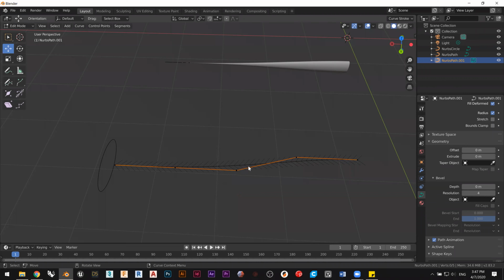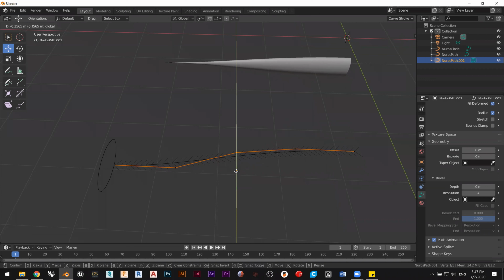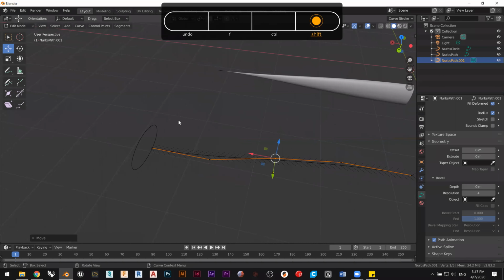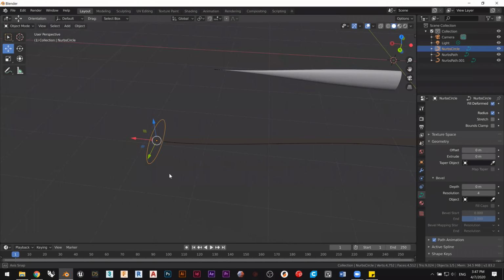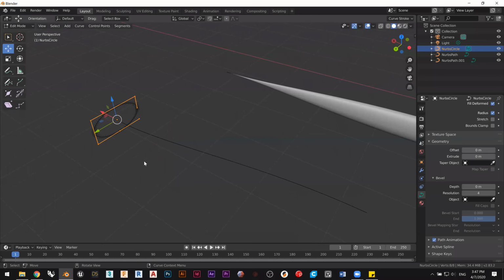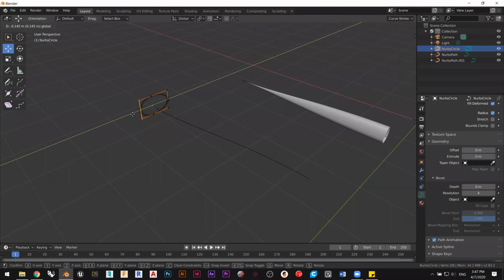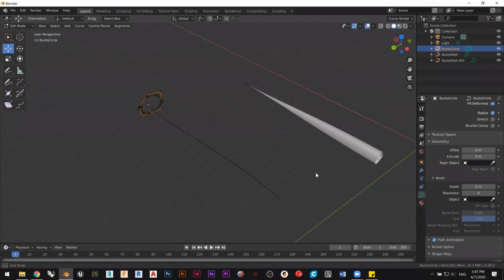So if I select my path here, which controls the taper, and I select these two control points and move them like so, see how this changes? So in doing so, you can have full control over the form of the pipe, right? And let me hit tab again to get back out of the edit mode and hit tab for the circle here. And kind of play around with, let's say, these control points, just move them closer. These control points, move them closer. Maybe this one gets down. I don't know. So I can mess around with that in the section.